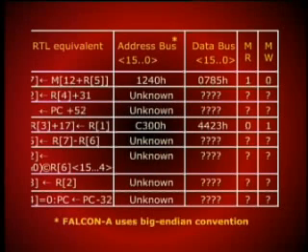In the same way, on data bus, as the instruction load is executed, the memory at location 1240 is to be read, and the contents of this location would be brought to data bus. And just look in the previous table, the contents at location 1240 are 785 hex. Now in order to execute and fetch read data from the memory, we must have memory read control signal activated. So MR in the next column is written as 1 and memory write must be 0.